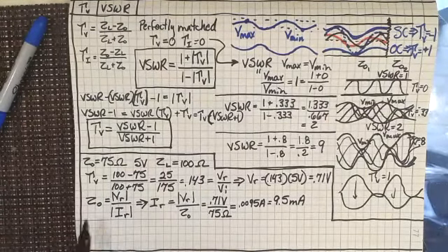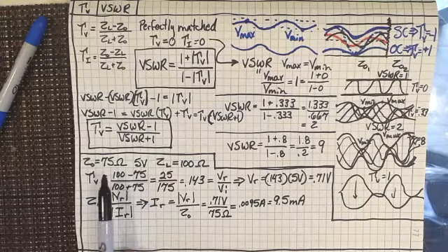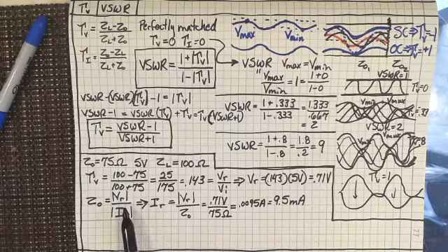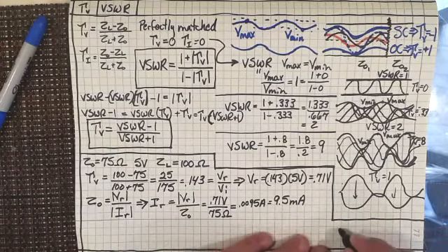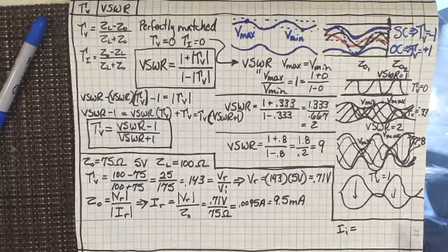Does everyone see how I did that? And I used the line impedance and everything and the reflected current. You know, we can do the same thing with the incident things. We know it's 5 volts and it's 75 ohms. So my current that's going in, I'll just write this down here for the current that's incident in there. I'll just put it over in the small little spot here.